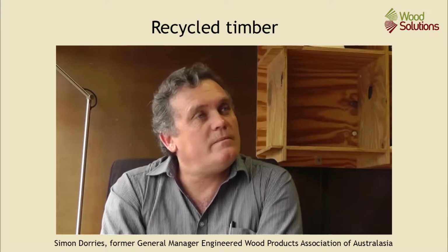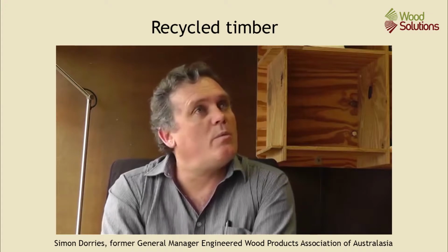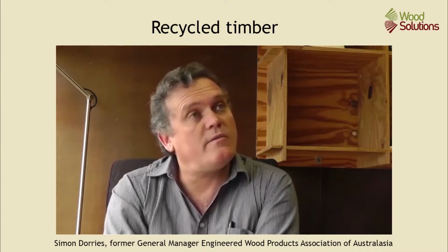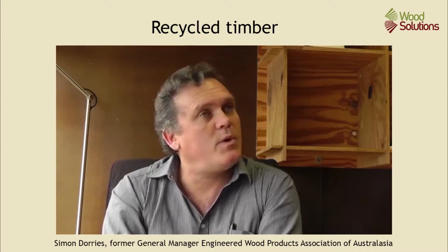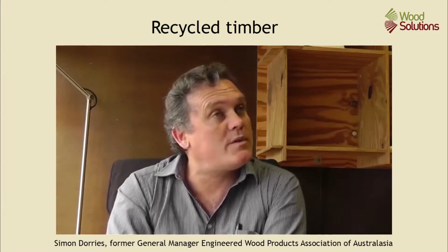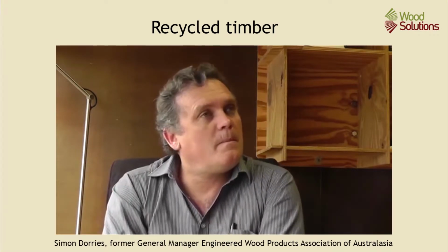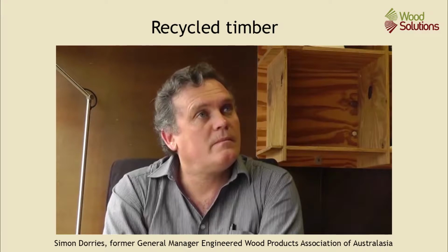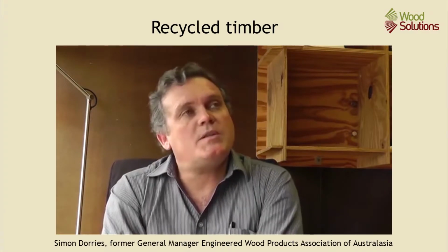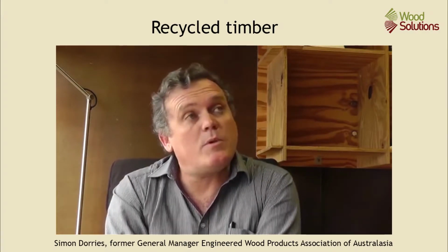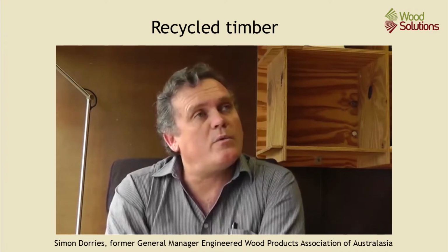So generally you'd use a D grade for concealed structural? Absolutely. Bracing plywood, for example, is a good application for D grade product. It has purely a structural function with no aesthetic values. So do these grades work across species? They work across species, so regardless of the species, whether it's hardwood or softwood, the same grading rules apply.